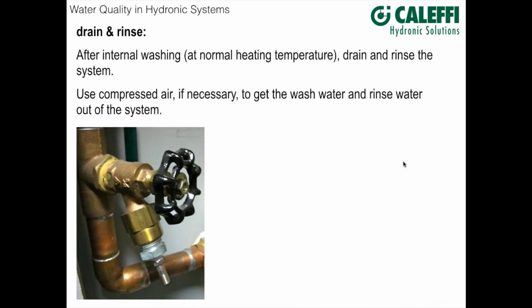Now, we've cleaned the solids out of it. We've done the internal wash. The next thing we want to do is a good rinse. All right, we want to get that water, especially water that has the hydronic detergent in it, out of the system.